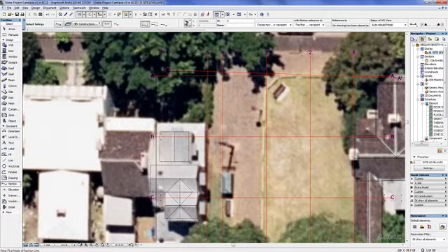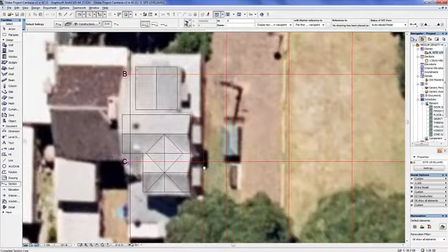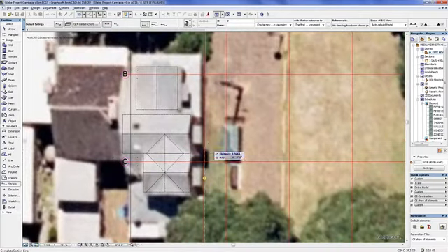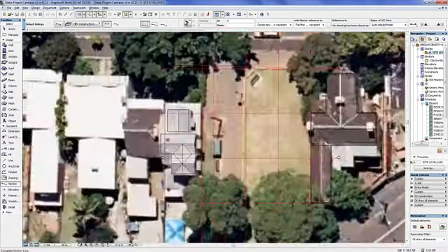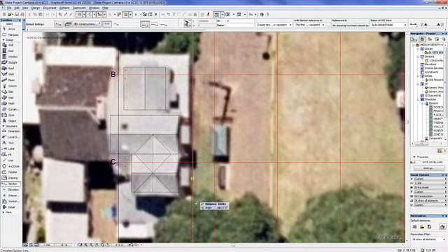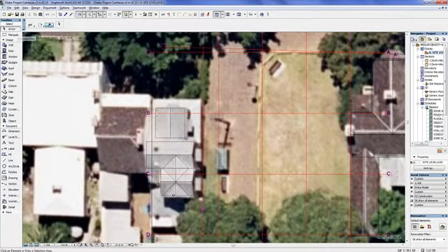And when I say section, I mean just drawing a section line that is parallel to the grid, because your building is parallel. Remember, this is not going to follow this grid line number 5, because grid line number 5 is not parallel, if you recall from when we first drew the survey based on the site survey that you were given. So I've just drawn a section, and the way I drew the section was to draw the line. So click with my left mouse button, then click with my left mouse button, then click to the left of the line to indicate the section is looking left.